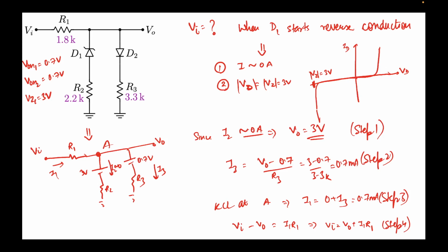Yes, again, there are a few things that we have assumed over here. Here the current will continue, here the current will also rise. But in our model, on the right side it rises exponentially with Vd. In all our models we have assumed that R on is equal to 0, because we have drawn it to be a vertical line, which is not the case actually. In reality, there is a slope over here, so that R on comes into the picture.